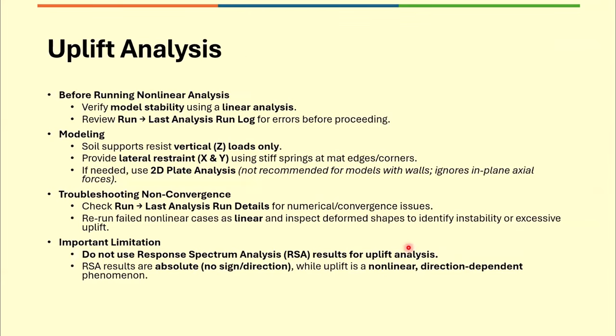And if you are performing uplift analysis, you need to ensure the model is stable for linear static analysis and review the analysis run log to ensure everything is fine. The modeling requires lateral restraints using a spring point, corner springs or line springs that resist the lateral displacement.